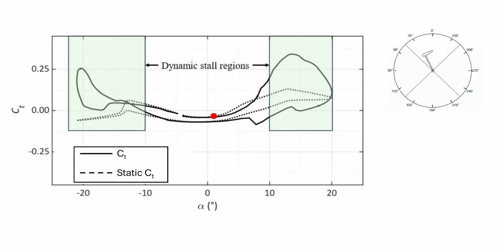The main point of this plot is to isolate the effects of unsteady aerodynamics, or more specifically, dynamic stall. It allows you, the user, to really understand which regions are enhanced or are negatively affected by dynamic stalls. I'm quite certain that if you're studying dynamic stalls on Darrieus turbines, you'd eventually need to have this kind of plot. I've developed a special software module embedded inside Java to help me compute this static thrust coefficient. It took me just a few seconds to come up with these plots.